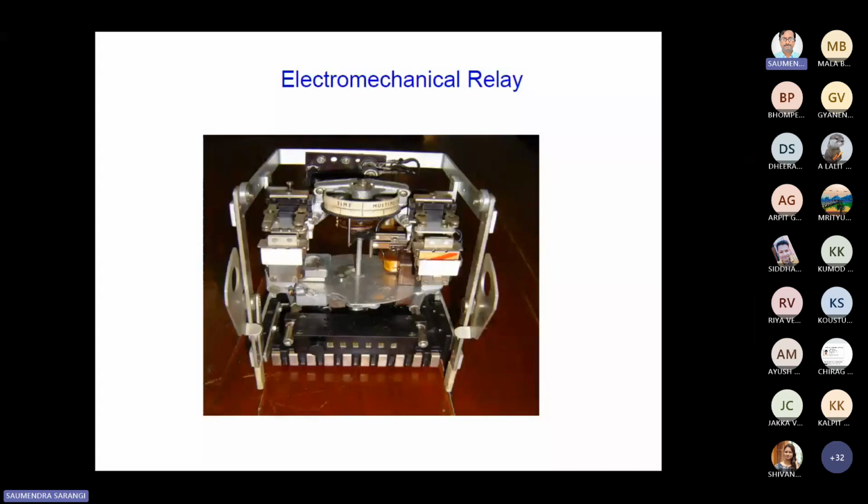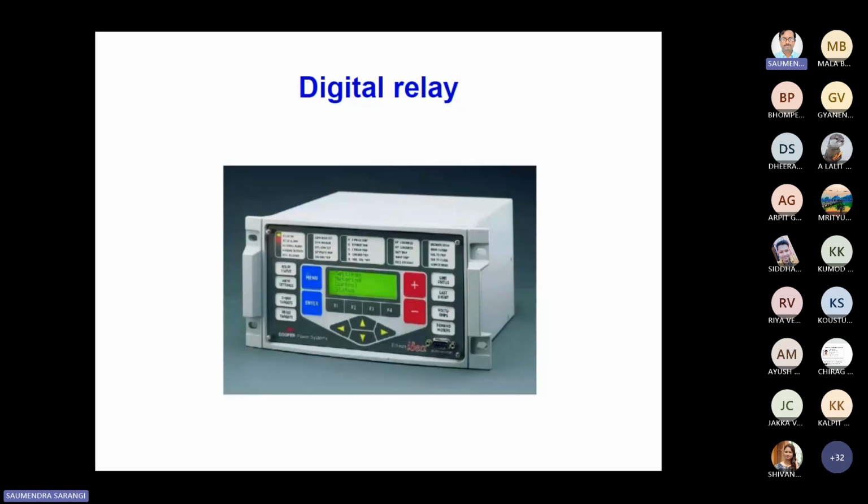Okay, so this is a digital relay we are having. Digital relay, basically, will also have a battery supply. Two supplies should be there. One supply will be from our main supply, called the power system supply. The other supply, the auxiliary supply, is basically a DC supply. That DC supply is utilized whenever a power system fault occurs and voltage goes down, so we cannot sense anything, right? At that time, if you are having DC, then according to whatever inputs are there, this digital relay will take a decision.